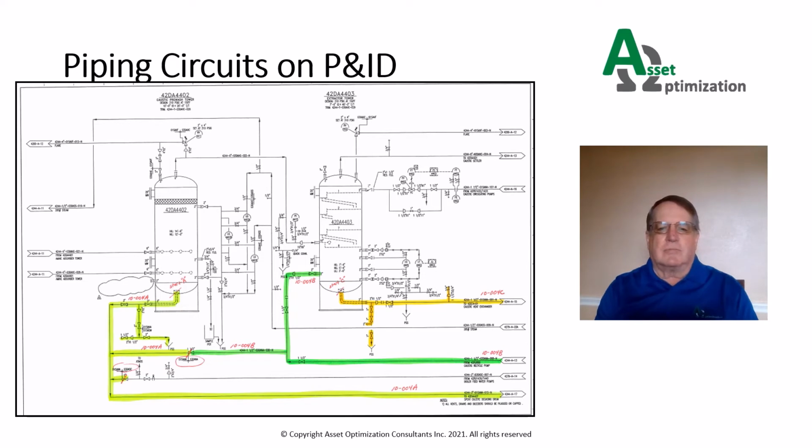Once the piping systems are documented on the PFDs and P&IDs, the next step involves splitting the process-based systems into corrosion circuits, which are defined as a section of continuous pipelines exposed to an environment of similar internal corrosivity, similar operating conditions, and similar materials of construction. Circuits typically start and stop at pieces of fixed equipment. One exception is a spec change where the material of construction changes. Then the circuit may start or stop at a flange connection.